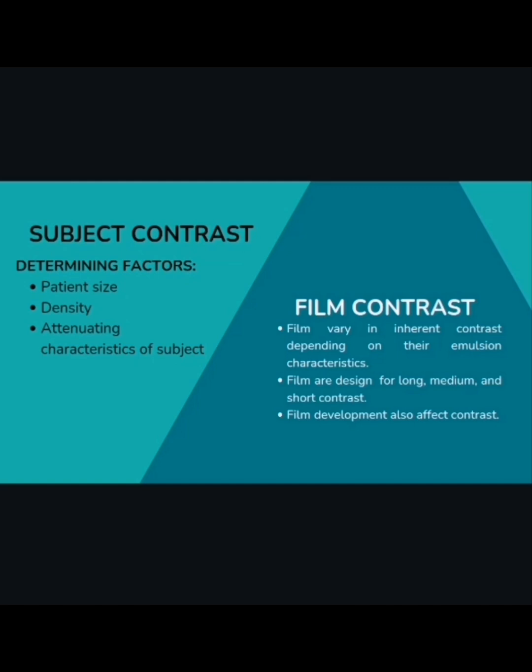And now, we have film contrast. Film contrast varies in inherent contrast depending on the emulsion characteristics. Films are designed for long, medium, and short contrast. And film development also affects film contrast.